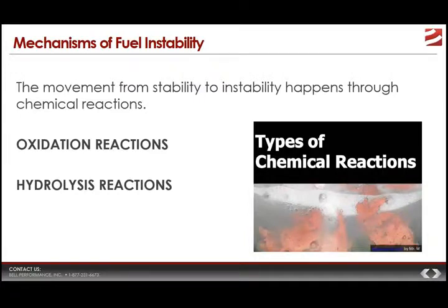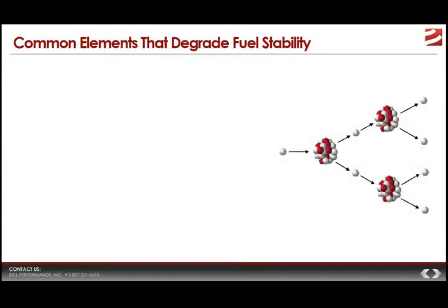But why does that matter? We say, so what? Well, why that matters is because these stable molecules that are reacting start linking up, they start reacting with other molecules, and they start forming longer and longer polymers or chains of molecules. And eventually these molecules get so big that they're no longer able to stay soluble in the fuel, and they drop out.